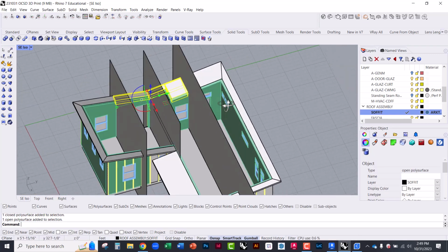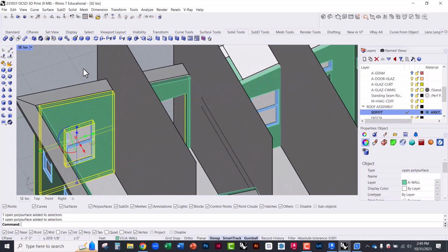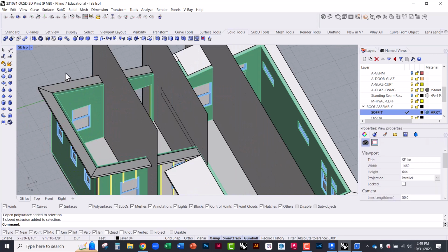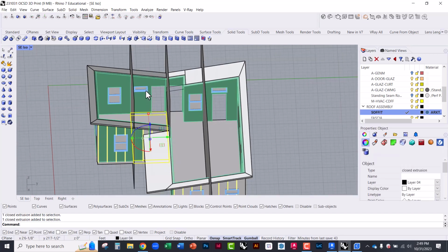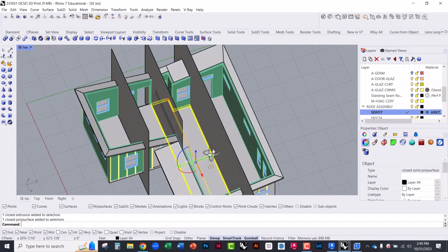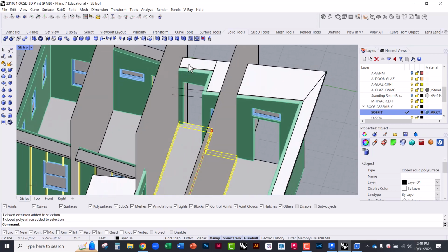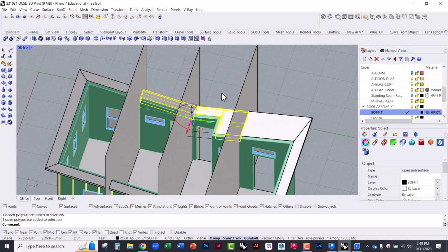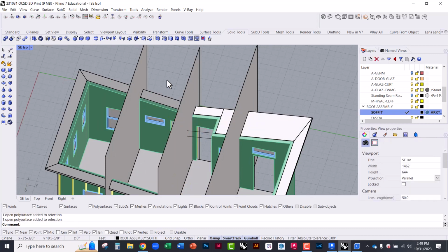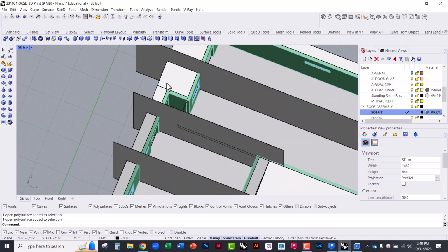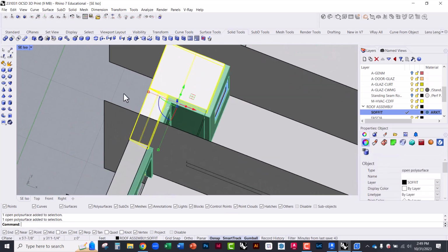So what I'm going to do is do that for all of the walls, do that for the floor. Actually, the floor I've modeled that way, so you won't have to do that. But you're going to take this geometry, type split, select the cutting object, and now this is two objects. So the cap command is a really useful one.